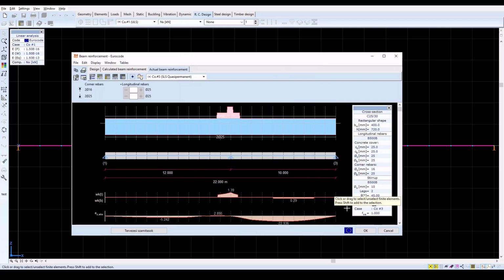The results for deflection are an approximation, since creep is calculated without considering the effect of shrinkage. A more accurate calculation can be made by nonlinear static analysis, which won't be covered in this video. A detailed description of how to compute a nonlinear static analysis can be found in the PDF Beam Model Tutorial Guide on the AxisVM website.